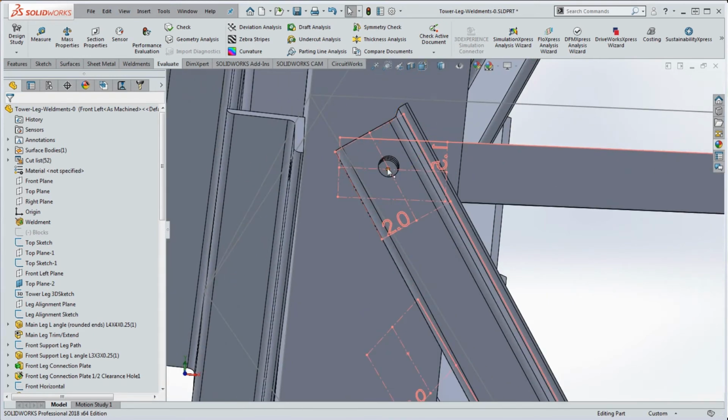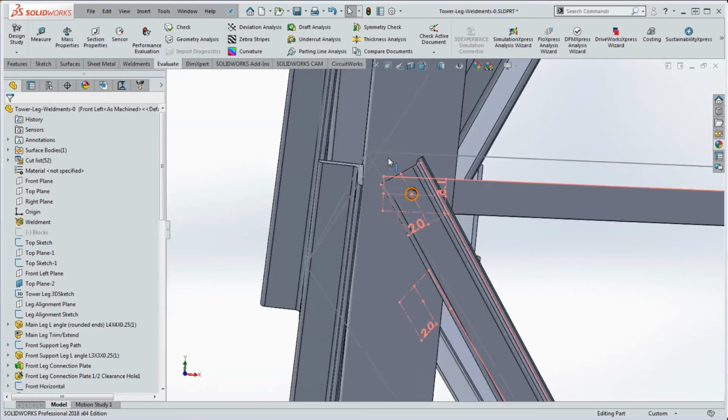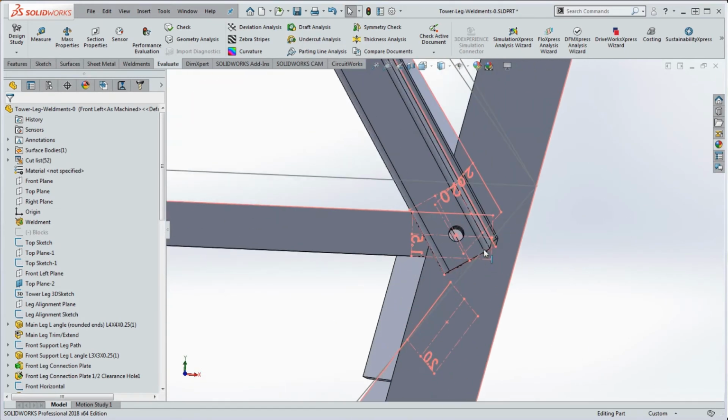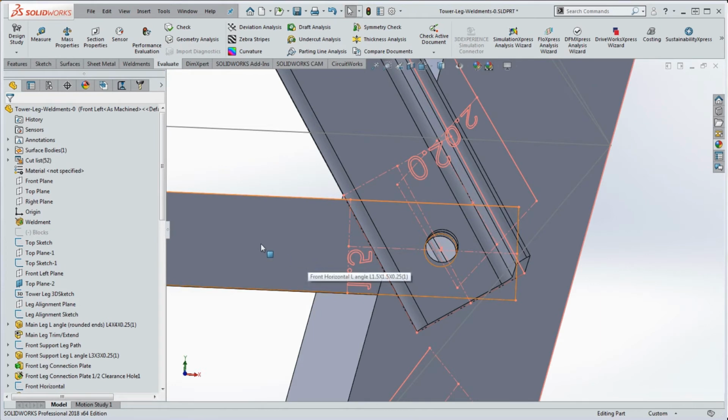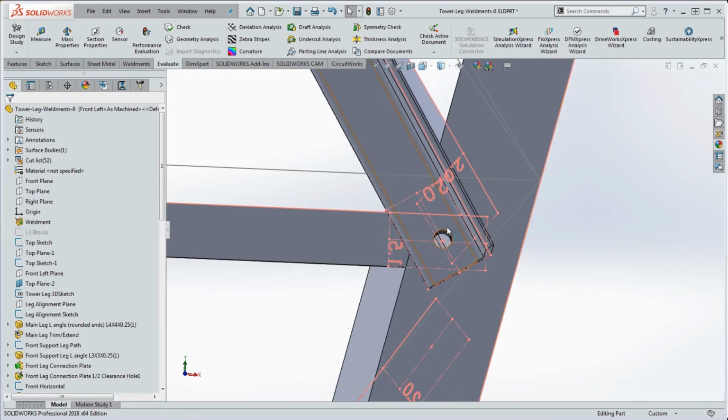But it's actually based on it in a peripheral way, because once we get that 1.5-inch horizontal in here, we're simply going to be dropping this structural member path segment with the sketch blocks, reference geometry sketch blocks in either end of that, right on top of that alignment point. And eventually it's going to be a hole within hole location. So this is defined simply by the point up here on that 1.5-inch horizontal, and this point down here on this 1.5-inch horizontal down here. So if we change that 1.5-inch horizontal, that 2-inch diagonal gets changed too.